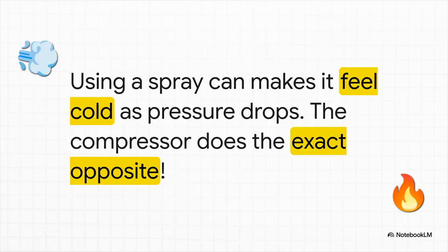You know how when you use a can of spray paint or compressed air, the can gets really cold? That's because the pressure is dropping really fast. Well, the compressor does the exact opposite. By jacking up the pressure, it also jacks up the temperature. It makes that refrigerant gas super, super hot, way hotter than the air outside.